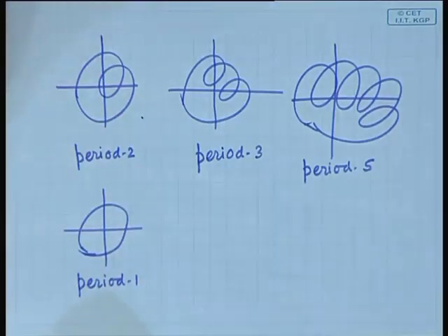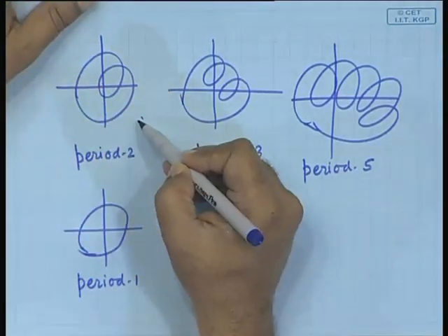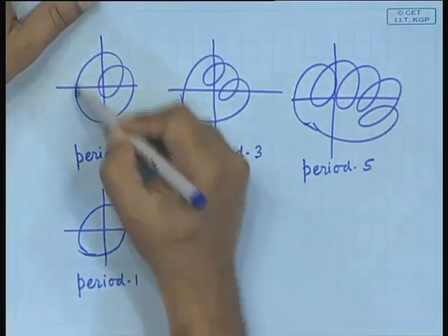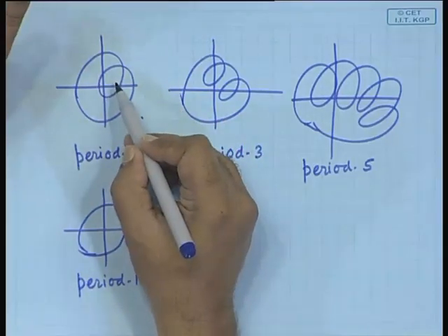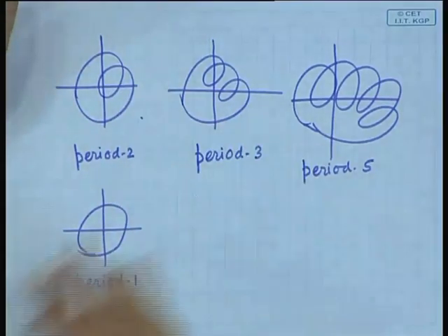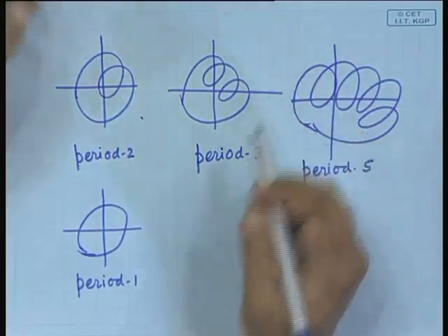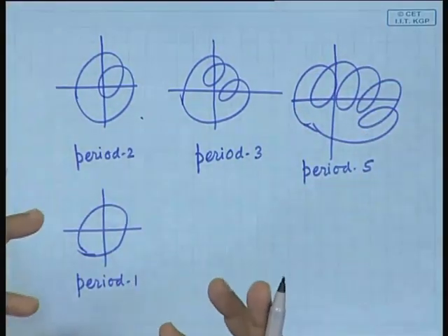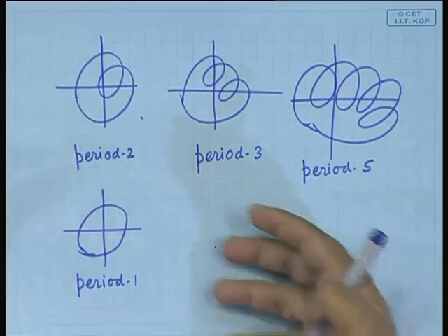Starting from any initial condition you go on, but if you start from another initial condition here, what will happen? If it is a limit cycle, then it will converge onto that; it will slowly, progressively go closer and closer to that limit cycle, and finally it will converge onto that. In that sense, this is also a limit cycle. And we have said in the last class that these are sort of gravitating bodies in the state space, in the sense that if you start from another initial condition quite far off, it gets attracted to this.